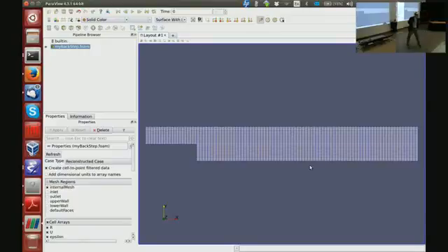You want to copy my numbers or you're working it out yourselves? Copy my numbers? Work it out yourselves? Cool. Okay, any problems with this mesh? Well, I'd like to have it a little bit less uniform. For example, I know that all of the interesting physics will happen here, right? So I would like these cells to be bigger than those cells, and those cells to be smaller than these cells here. Okay? So for that, I am going to use the grading option.